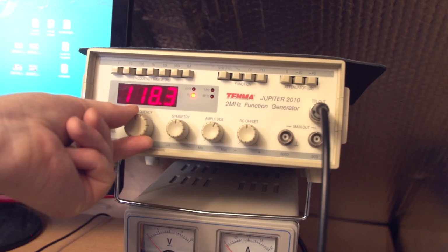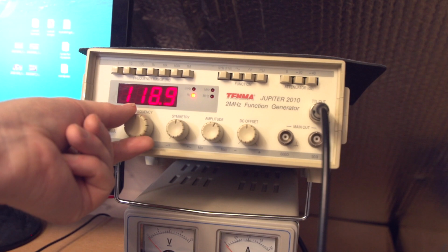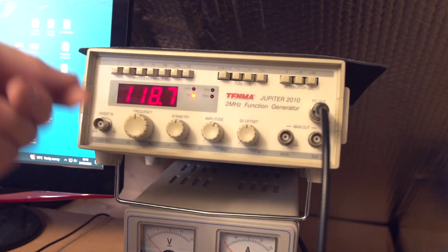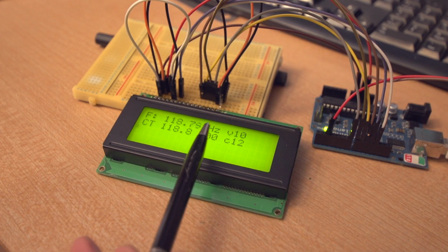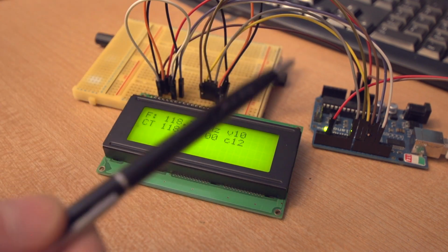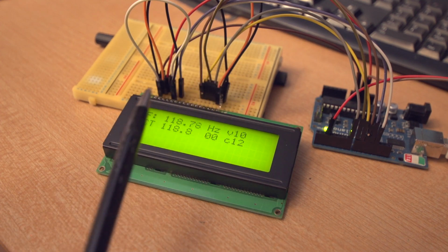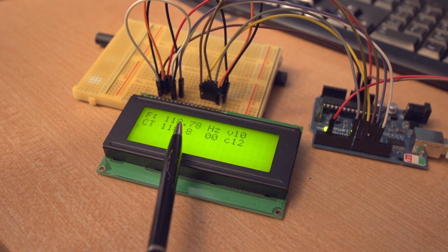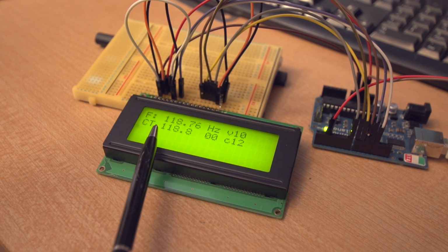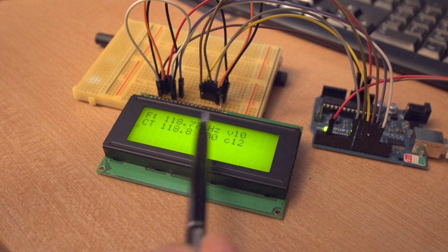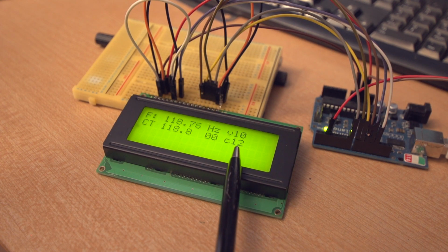If I set this to one of our local repeater channel CTCSS tone frequencies, the local one where I live here is 118.8, or 118.76, and I'm looking at the signal generator over there, and it does actually say 118.7, and this is saying 118.78 in fact. So the frequencies are correct. It's telling us that it's looking for 118.8, which is one of the channels it's recognized. This other information we can ignore for now. That's debug information coming from the software.